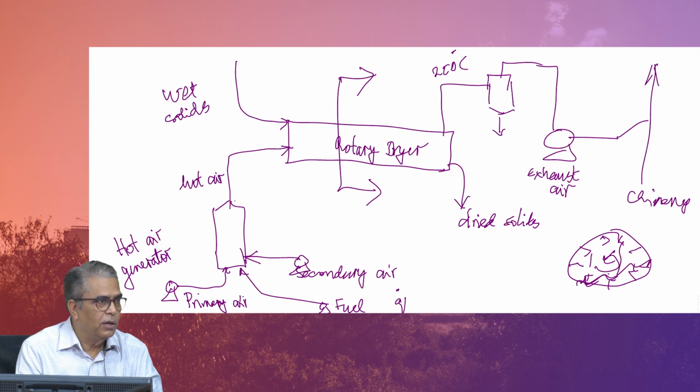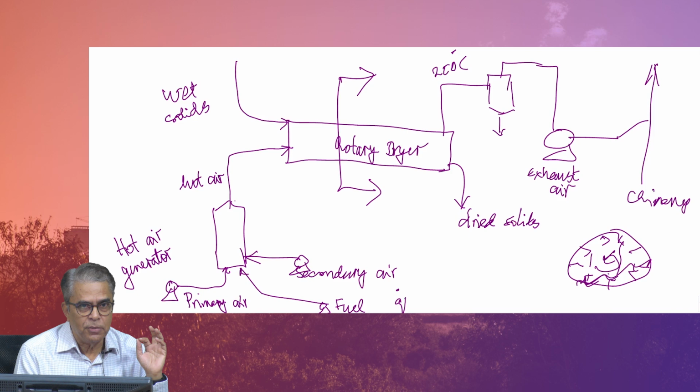So, you will get some quantity of the primary air, but do not worry about that, because that calculation is not required for this purpose. But you will find that the air quantity will, along with fuel burn, result in a hot product whose temperature can you calculate? I know the fuel quantity, primary air I am assuming 100% efficient, so no excess air. What will be the resultant temperature of the mixture, can we find out? What is the principle we will use here?